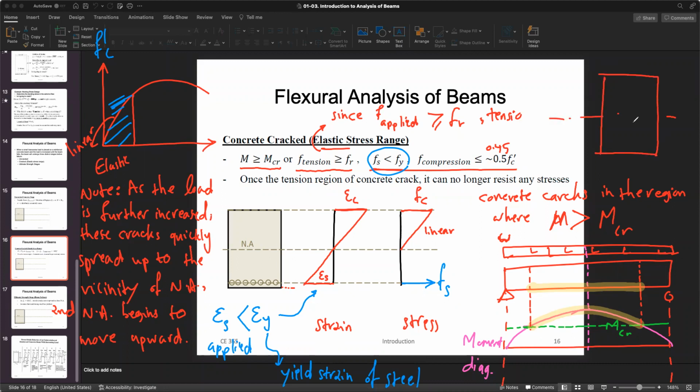All right, this is your original neutral axis, let's say. So you start to see cracks here, here, here, here, and here. So what is happening? When you are cracking this much, the concrete left would be this portion, the clean concrete.